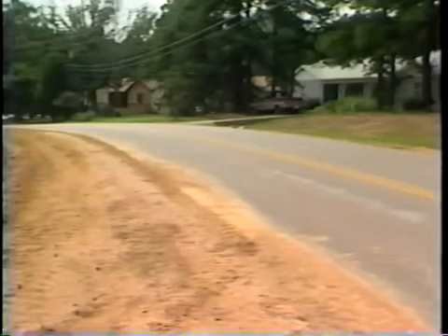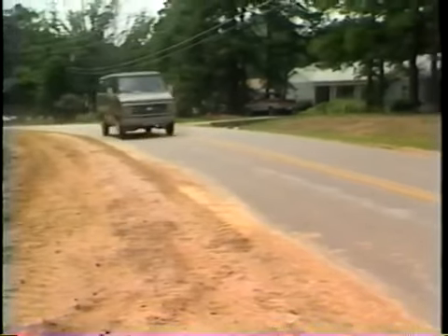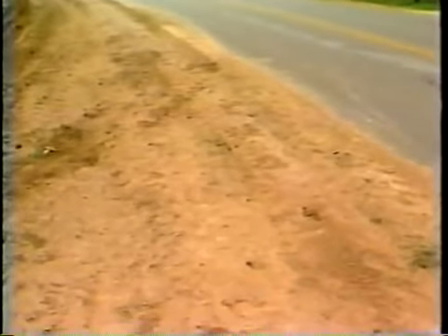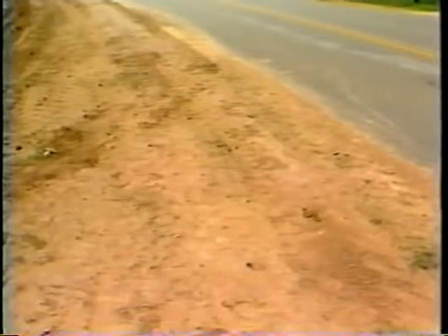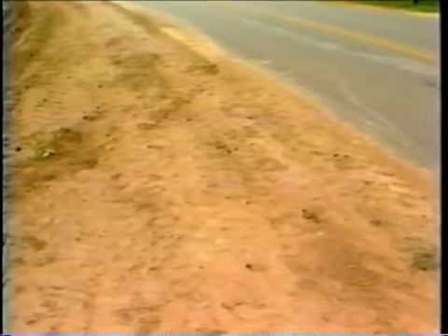The reshaped, unpaved shoulder has a smooth transition. It is properly sloped toward the front slope of the ditch. The shoulder is now smooth, with no unevenness, ruts, corrugations, or depressions.